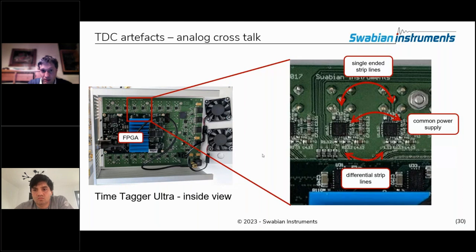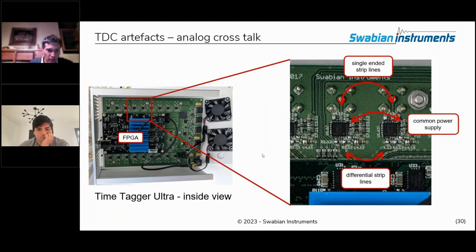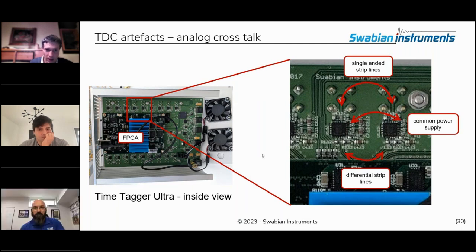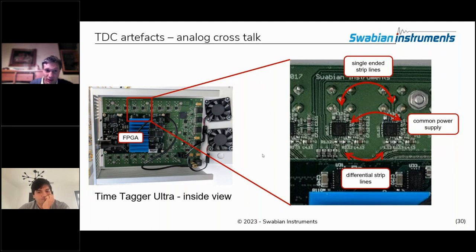And indeed, to get this right, whenever we release a new bit file, we really test the crosstalk between all sorts of channels by letting the FPGA run with random input signals for almost a week. So that makes the continuous integration quite heavy. Before any real bit file release, we heavily test the crosstalk for about a week, because if the routing inside the FPGA changes and routes really cross, you can get quite some heavy crosstalk. So that's really part of the homework that you have to do. Okay, so that's analog crosstalk.